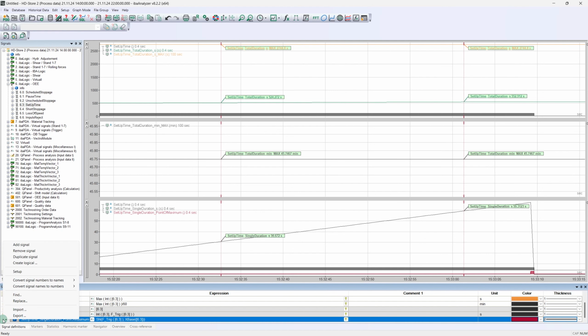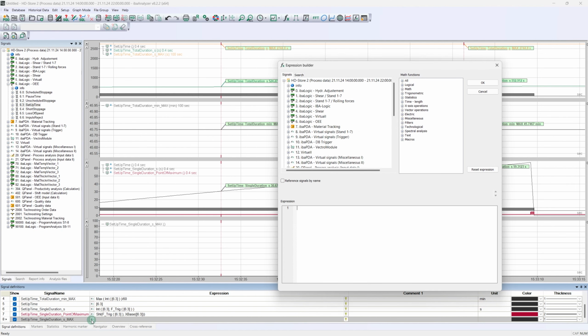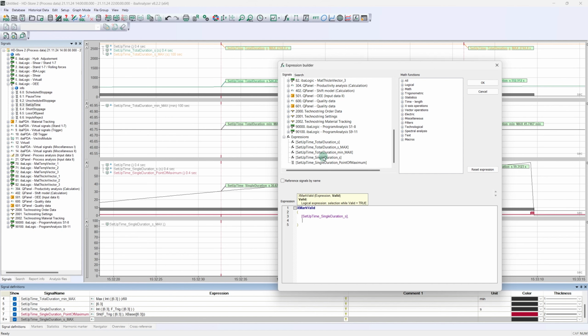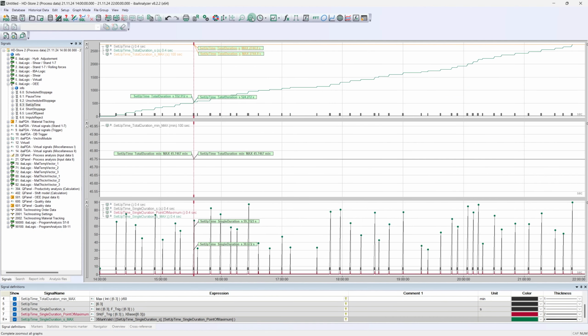We can now use the result to mark the maximum values. We use the xMarkValid function for this. We already used a similar function in the previous example. To be able to use the result later, only one step is missing. As we are currently dealing with individual measuring points, but we can only process signal series, we have to close the gaps with the fillGaps function.